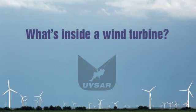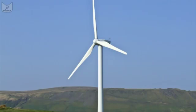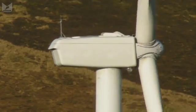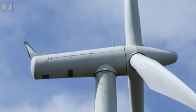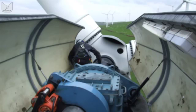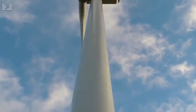Welcome. In this video, we'll show you the layout of a typical wind turbine generator as found on wind farms across the world. Now, exact designs do vary, but almost all the turbines in use today are horizontal axis machines, which have a three-bladed rotor spinning in a vertical plane attached to the front of a box which we call the nacelle, after the fairing around an aircraft engine. And in this nacelle we have the generator, often a gearbox, and occasionally a high-voltage transformer, and the whole thing sits on top of a tower, which is mostly there to keep the blades from digging a hole.